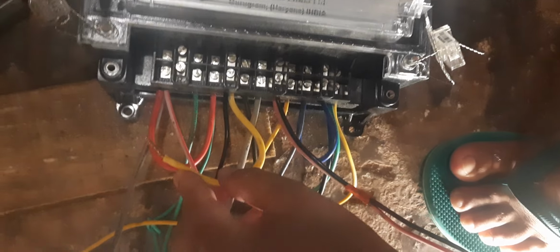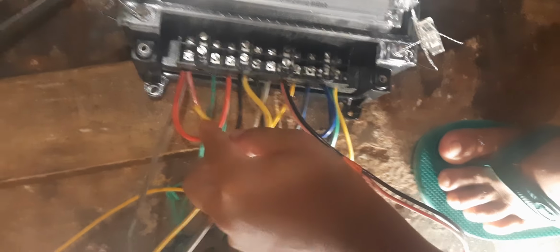You will have to give to this only. Details of these you will find. If I give the PT supply, then you see it will blink very fast. That means both the PT and the CT are important to a meter. If in case CT or PT is missing, then you will have to give additional unit. It does not mean that just because the CT secondary current is there and PT is missing, the meter will record the full current.